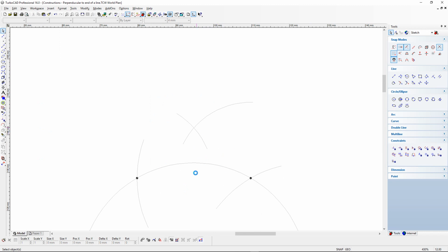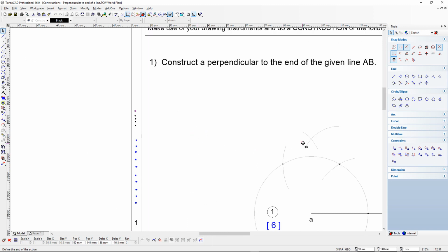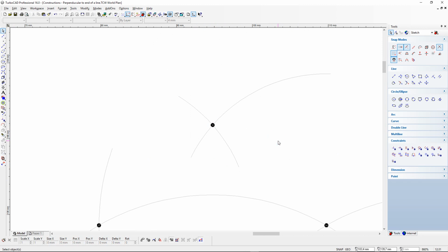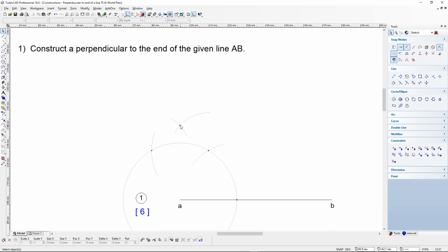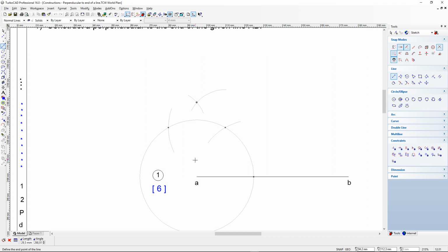Now I have, in the middle of these two reference points, a bit upwards, a reference between the two arcs that I've just drawn, and I'm going to draw another dot to indicate that intersection between the arcs that I've just constructed. And this will be 90 degrees right above starting point A. Therefore, I'm going to take my set square and use the 90-degree angle of my set square and draw a perfectly perpendicular straight line from that intersection down to starting point A of line AB.